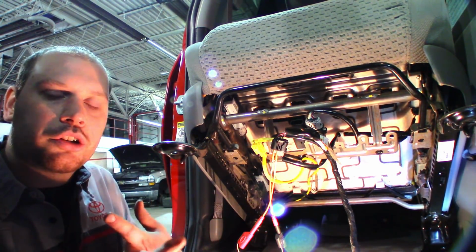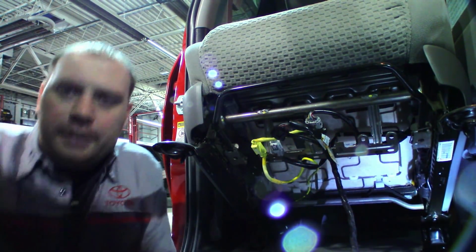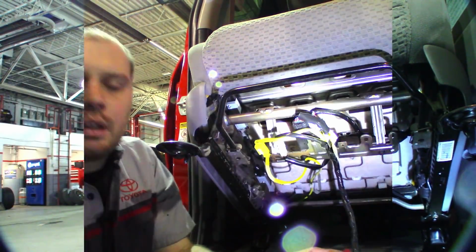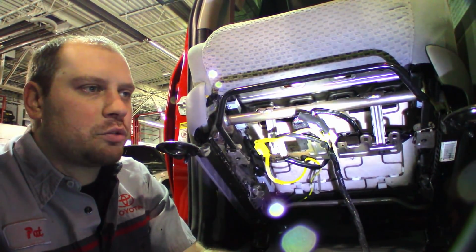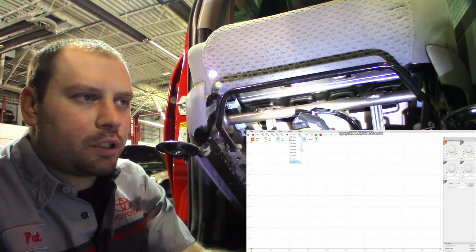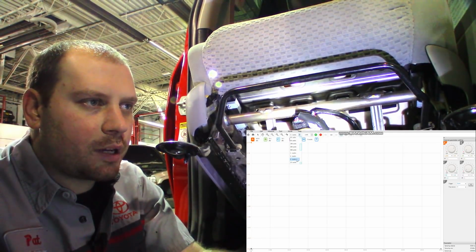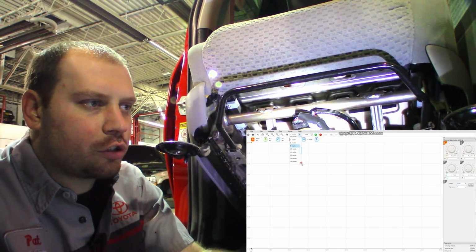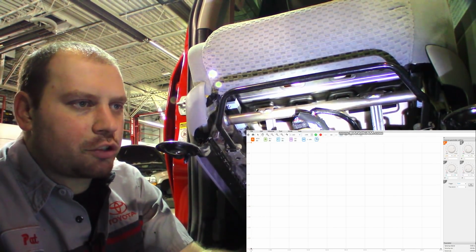The next thing I'm going to check is my communication wires. I'm going to grab my scope for that. So I'm using my Autel scope again. Everyone seemed to like it in the last video. Got this on a 20 volt voltage scale. I'm going to put this on a long time base. Let's do 1 second per division. Connect my scope.